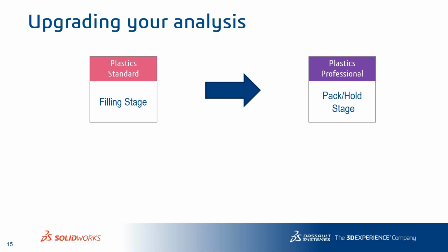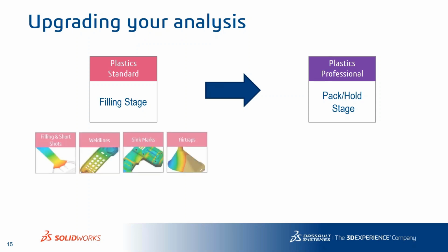In terms of the software itself, the way we position plastic standard and plastic professional is, plastic standard goes pretty much in line with that filling stage. Everything that you're concerned about in that filling stage can be included as part of that plastic standard setup. And then you have your pack and hold stage as part of the analysis, and what type of results that pack and hold stage gives you. So filling stage, again, weld lines, sink marks, air traps.